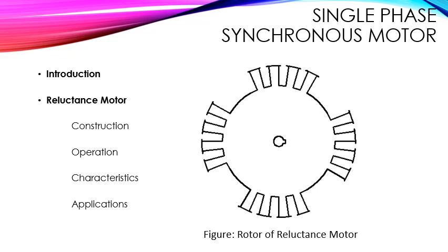When single phase AC supply is given, the motor starts as an induction motor, then accelerates and reaches a speed very close to synchronous speed. The slip is negligible when the mechanical load is small and the revolving field permanently magnetizes the salient rotor poles, right? So whenever the single phase AC supply is given, we have to know that the motor will start as an induction motor, right?